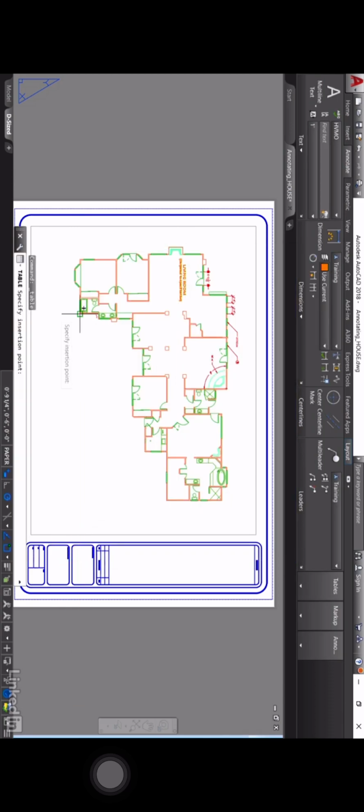Now you'll notice in the settings from the table style, we've also got a title and a header row there as well. And you'll see why those kick in a minute. They're slightly different sizes. And what we can do is we can adapt the table style to highlight things and change things if we want to in our title, header and data cells in the table itself. So make sure that your first row cell style is title, second row cell style is header, all other row cell styles data. So when I click on OK now, there's my table waiting to be dropped in.